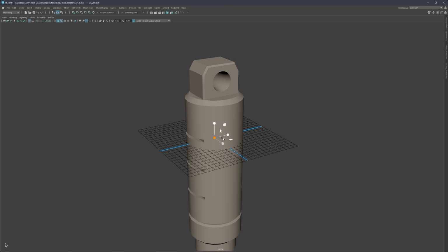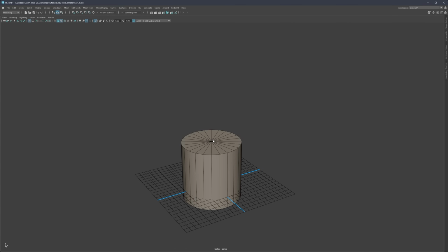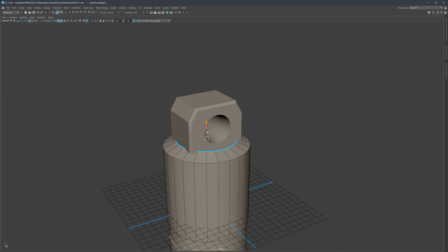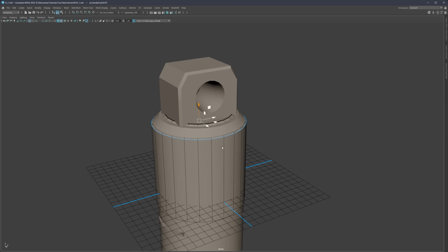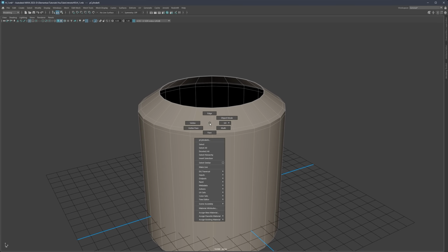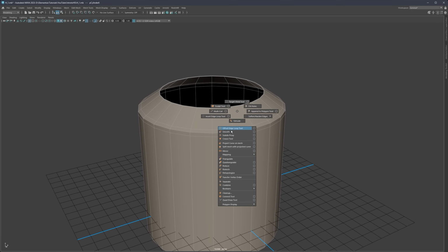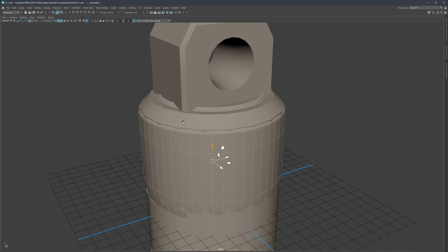I'm going to immediately hit my scale tool and try to push it here on the top, Control 1 to isolate, and I'm going to do exactly the same quick test. So let's go to edge mode, double click the edge mode, hit scale tool, extrude on the inside, and maybe push it a bit more to the top, to the bottom, and I'm going to bevel this real quick, and let's Control 1 to isolate, go to object mode, smooth, just in case we decide to smooth this later.